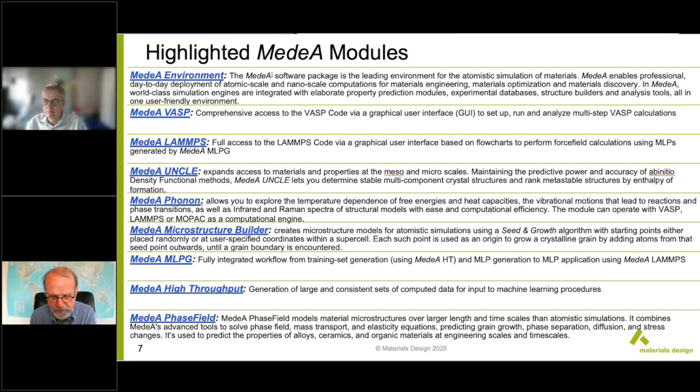So, for example, you start with a BCC structure and an HCP structure, and you say, well, you can populate now and replace the tungsten atoms with a rhenium atom, for example, and create different structures. And then the system automatically learns, and by creating structures, estimating the energy and picking the lowest energy to do DFT calculations and bootstrapping itself. So it's a self-contained automatic procedure in UNCLE.